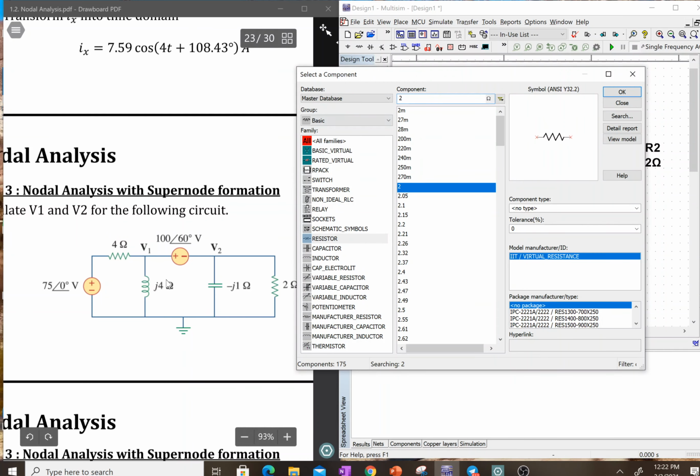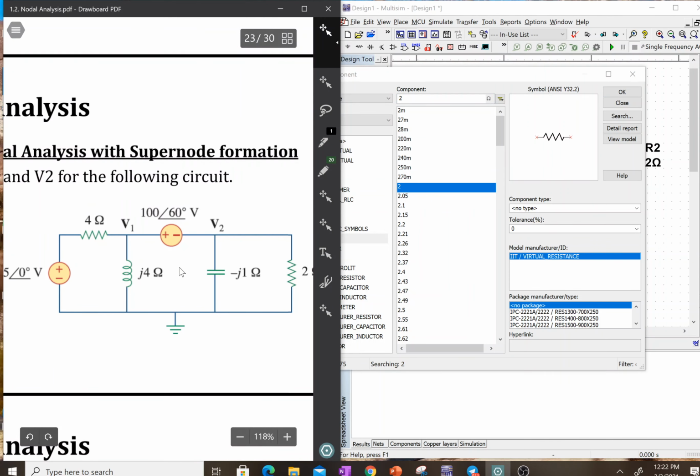And then next we need the inductor. Okay, J or 4J inductor. Okay, so this one, since the value given is a reactance value, we might need to calculate what is the value for the inductor in Henry and the capacitor in Farad. It's opposite. Capacitor in Farad and inductor should be in Henry. Okay, so substitute in the formula to calculate XL, which is J omega L.